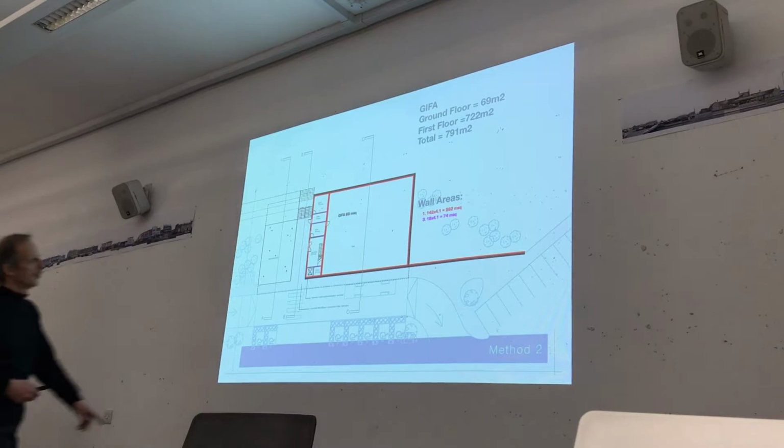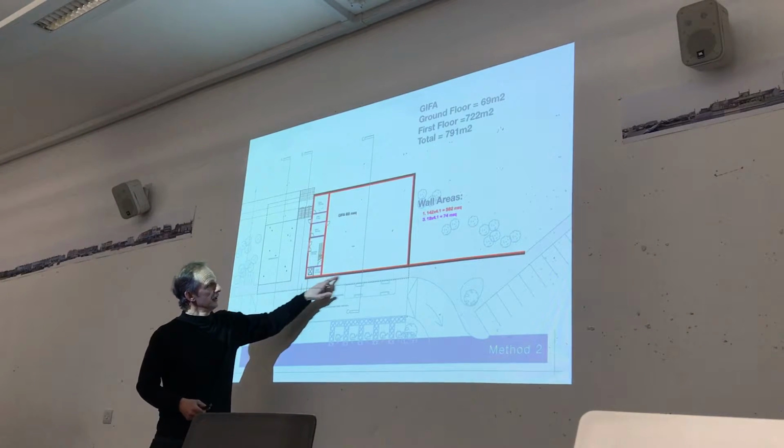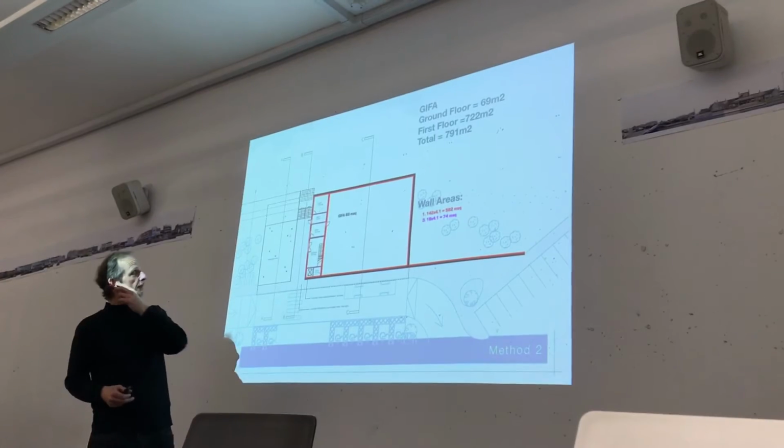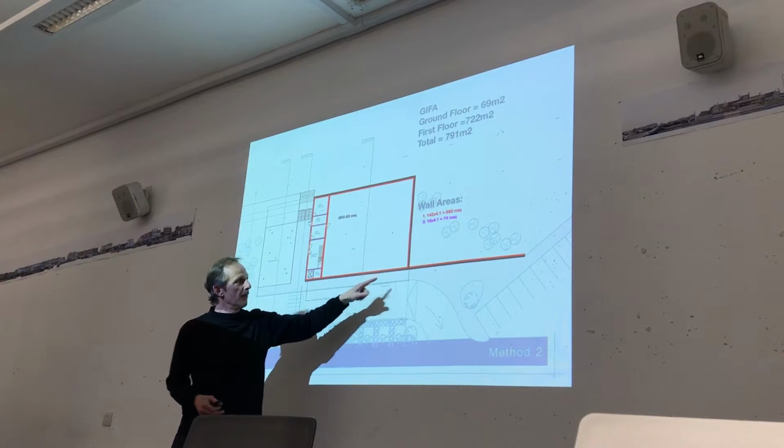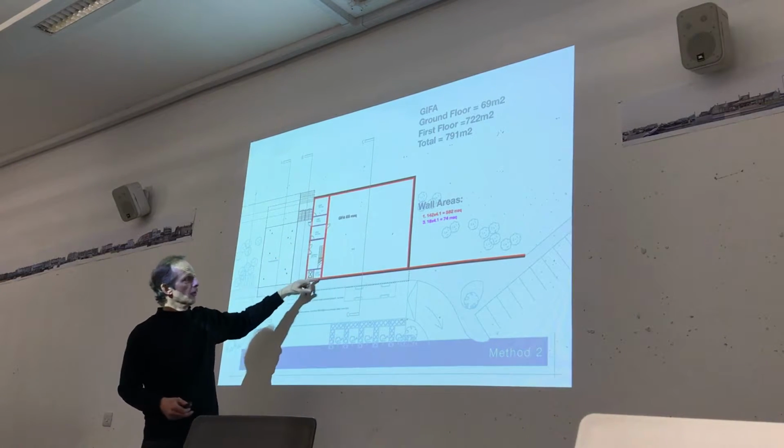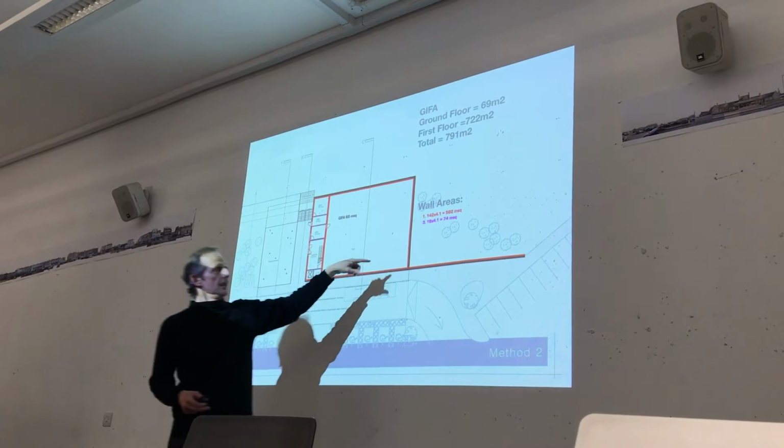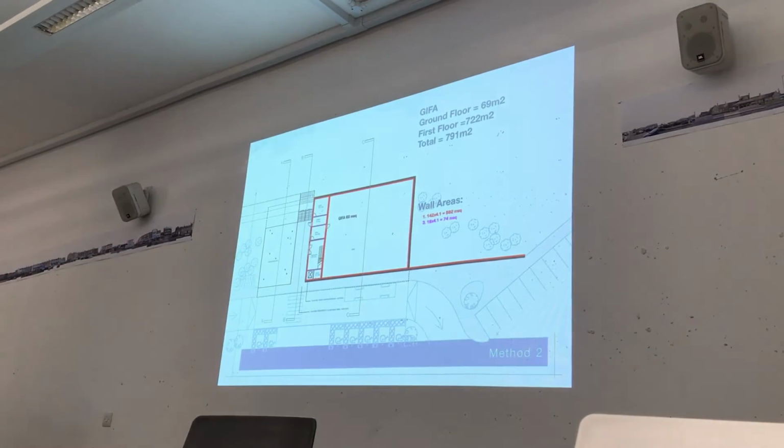So now we're actually measuring the whole of the area, the perimeter. This is all brick. So that gives us an area for that wall. So it's the perimeter length times the height, obviously, that gives you the area of that element. Does that make sense?